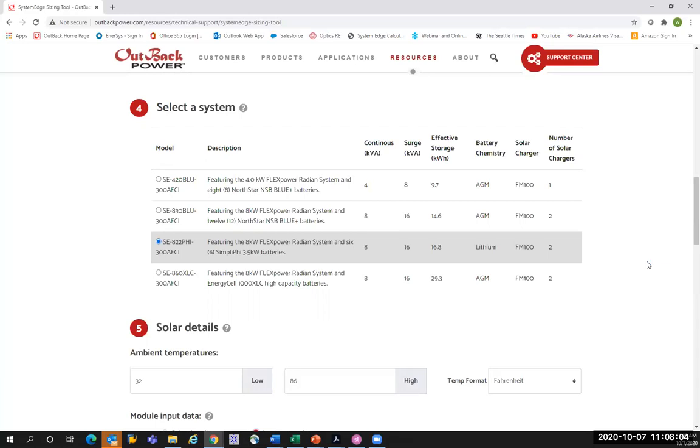Right. But I guess what I'm saying is, as long as we can handle that inrush, and you have multiple devices that have inrush, I wouldn't worry about it too much, because the chances of them all coming on at the same time are unlikely. But do look up that 100 millisecond spec, and also go to the motor manufacturer site, because locked rotor is not the same as inrush. It can be. It's kind of like with batteries, I found what some people call absorbed, some people call bulk. So make sure that locked rotor is actually what that motor manufacturer is calling inrush.